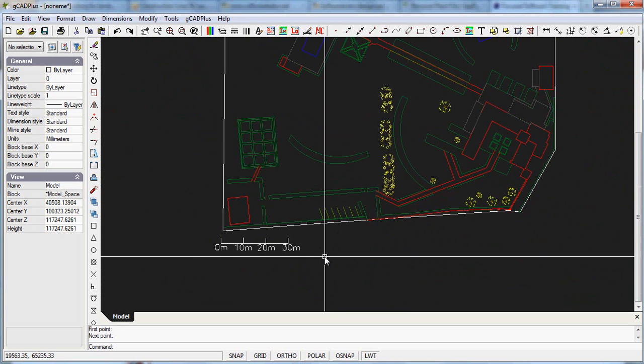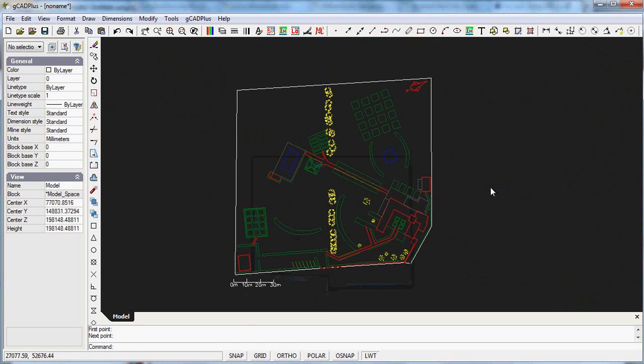So I'm pretty happy. We now have a drawing that's clean, quick and efficient, and we're in a position now to do some layouts on, say, an A1 sheet. You may recall that I said it's best to put all objects in model space at full size and then create layouts where within the layout you take a snapshot of any part of the plan.